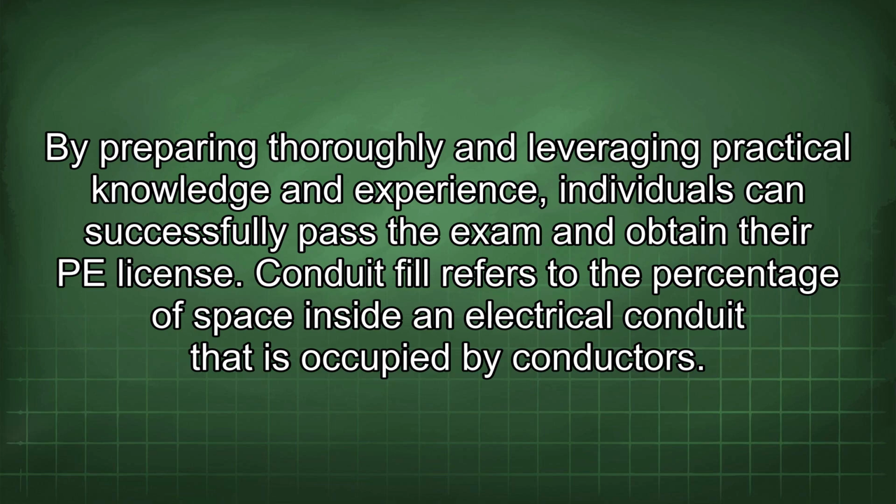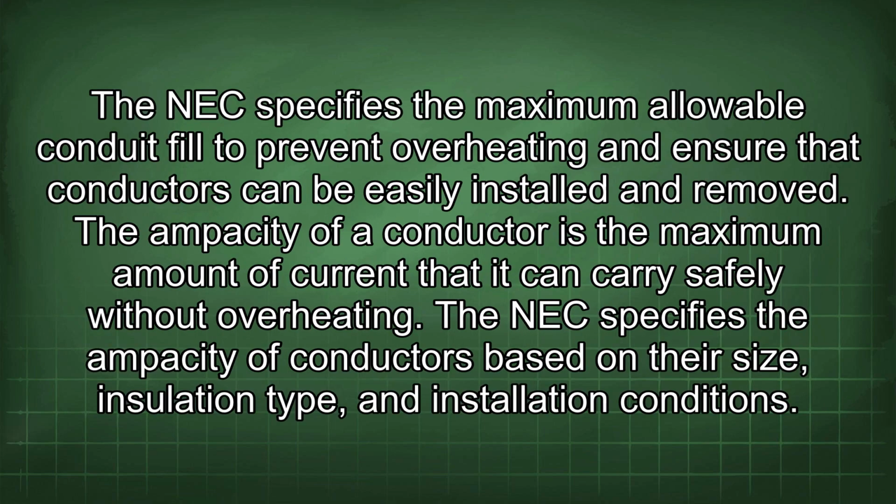Conduit fill refers to the percentage of space inside an electrical conduit that is occupied by conductors. The NEC specifies the maximum allowable conduit fill to prevent overheating and ensure that conductors can be easily installed and removed. The ampacity of a conductor is the maximum amount of current that it can carry safely without overheating.